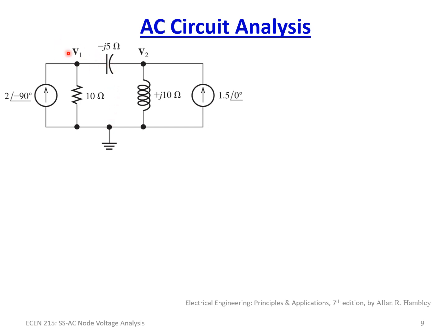Again, Kirchhoff's current law says all of the currents entering or leaving a node must equal 0. So all the currents entering this node, V1, must equal 0, or all the currents leaving the node, in this case V1, must equal 0. So we have to sum everything either entering or everything leaving. Personally, I like to do everything leaving, because you're starting at the node of interest.